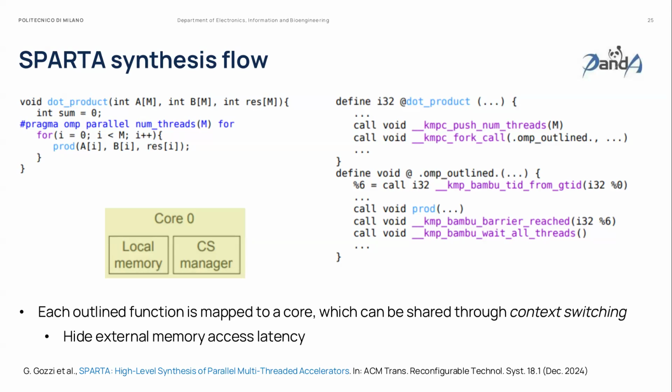So I believe it can be data flow, whenever the data is available, to just start something. No, I think that wouldn't work. Usually what you have is some control signals at the interface, and then the interface is towards external memory. What you would do in the host application is move the data to the memory where the FPGA will access it, and then you use some registers to set the control signals, and then the accelerator does everything else on its own.